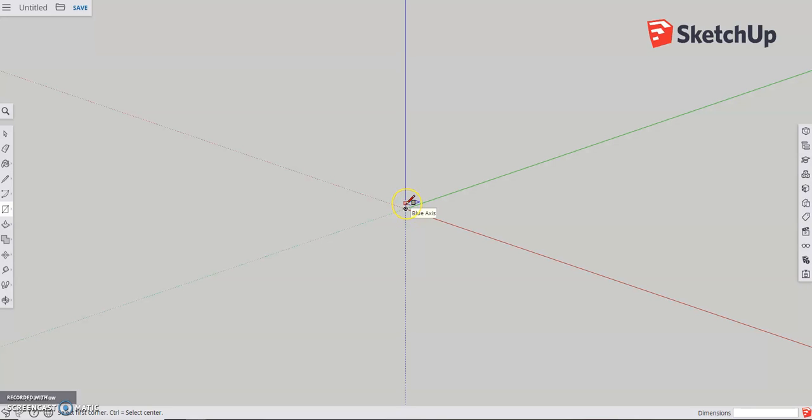When I draw an object, I don't want to hold down the left mouse button. I want to just click one time with the left mouse button on the origin. Then I should be able to drag my mouse around 4 different planes all along the green and red. Basically this lets me resize my object. If you ever see a line in the middle, that indicates that your object is now a square, and the length and the width are the same, and you will not be able to edit the dimensions because a square is equal on both sides. So make sure before you attempt this next part that you have something that looks like a rectangle, not a square. So I just put a rectangle here.